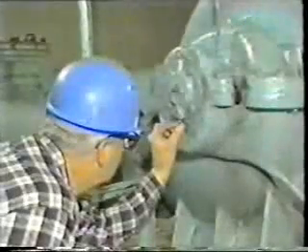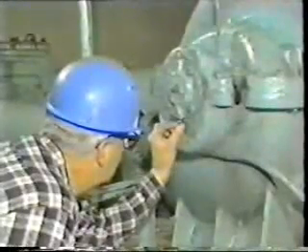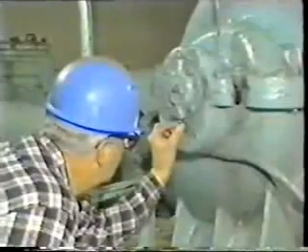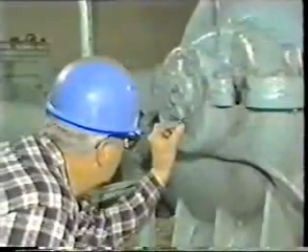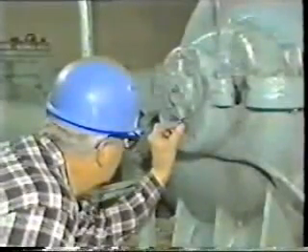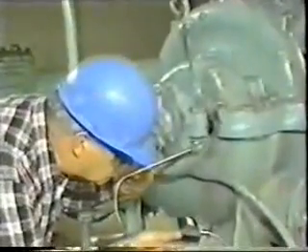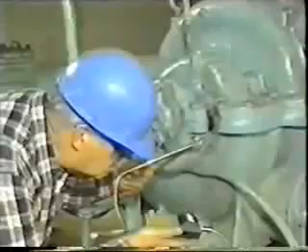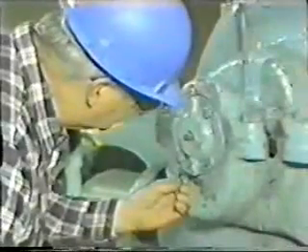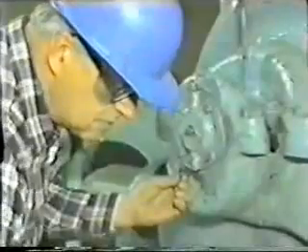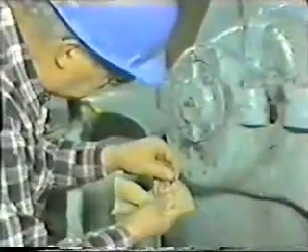If excess grease does ooze out, then you could replace the plug after all the excess grease has drained out. You would have to let the pump run for a while. It could take a while before the temperature would decrease, so you would have to monitor the temperature until it returned to normal. You should also check the condition of the grease to see if contamination is the cause of the overheating. You can do this by first rubbing a smear of grease onto a lint-free towel.